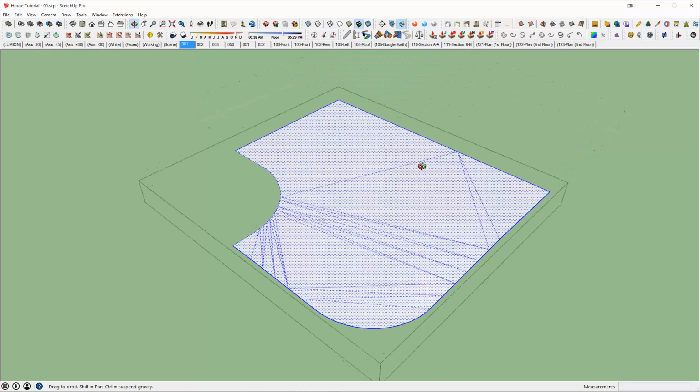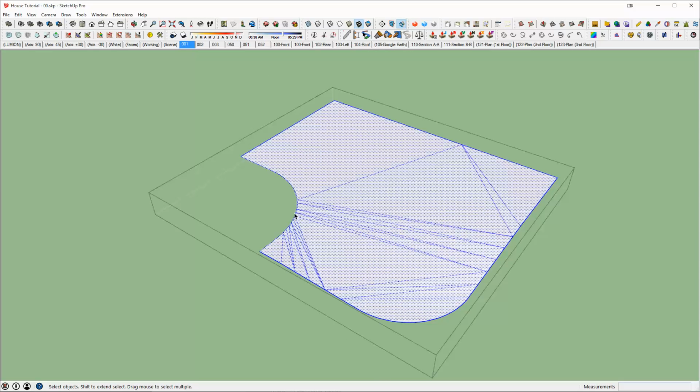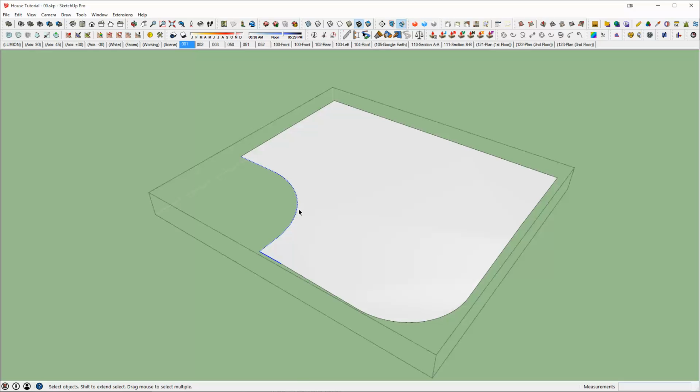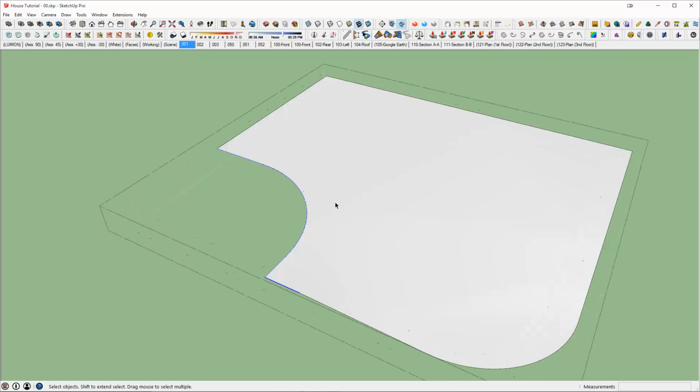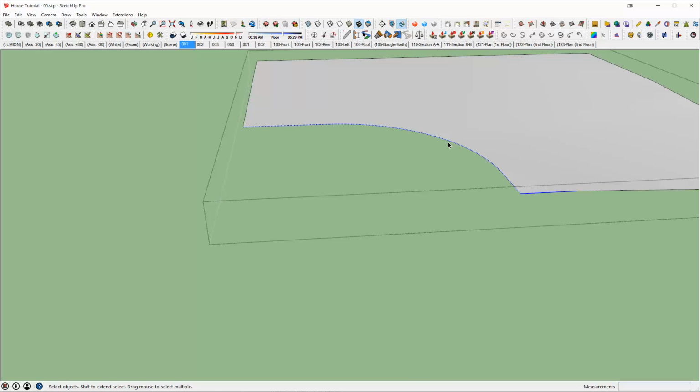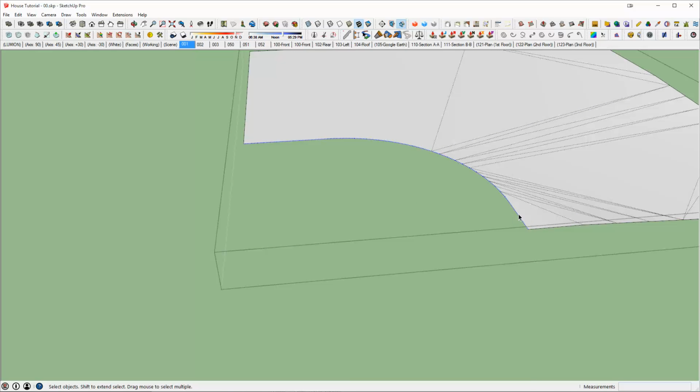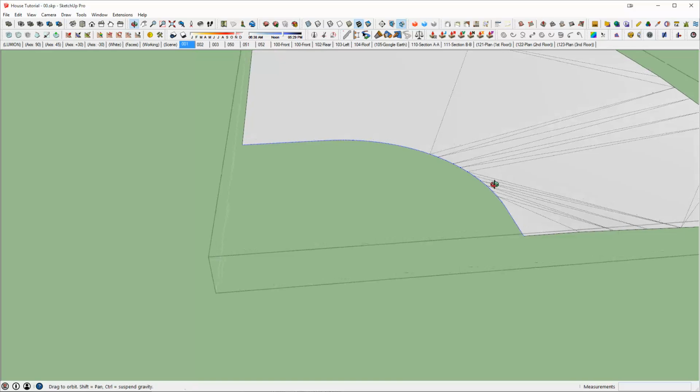I'm going to run my clean command, which gets rid of a lot of the erroneous material. Actually, this looks like it might need to, see if I can run my soften or unhide command. Oops. Let's see here. I think it's all hidden. Nope, it's all softened, so unhide.